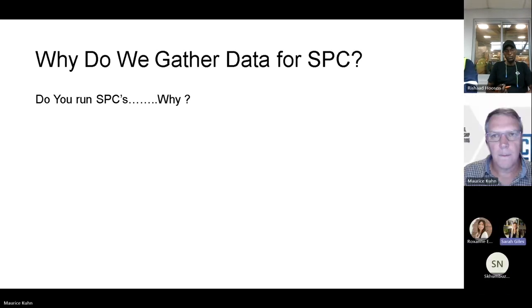Now the control charts also, I don't really like them because I also think it's a paper exercise. We've sort of automated it in a way that it alerts us, and once it's out of spec, it rejects the parts immediately and things like that, based on the data received. But your question, why do we run SPC? Is because we want to detect an out of control process before it goes out of control.